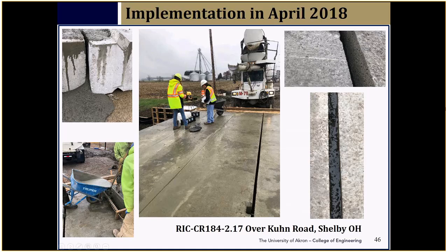One thing that really bothered the contractor was the amount of strength gain that we were requesting. So he said, I don't want to do anything with your mix design. We asked him, can you please at least come up with your own mix design and do a grout with 10,000 psi strength? No way, we're not going to do that. So they used our mix design that we used in our lab, which worked out very well in the end. But he was very concerned about the flow. So we did some trial mixing and trial placement, and it worked out really well.